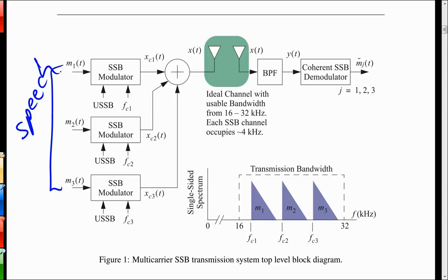And I'll explain that more as you get into this, because it's kind of like protecting the receiver from the processing blocks in terms of leakage signals and so on, interference. But the goal will be to demodulate either 1, 2, or 3 and minimize the interference from the other signals. So you'll be putting the 3 signals up on carriers that are somewhere between 16 and 32 kilohertz, so the simulation runs efficiently enough in MATLAB. It's not at a really high frequency, but it's up there a little ways.